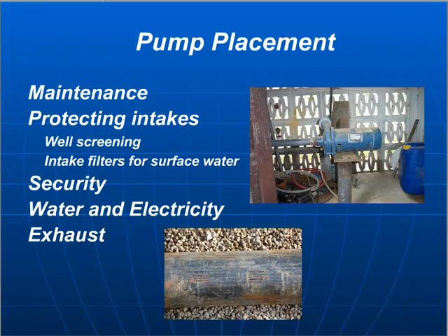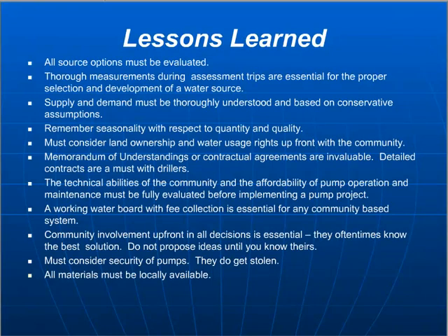It's also important to think about the housing of the pump itself, where it's going to be placed, and how it's going to be protected to ensure that it's not at risk for theft or vandalism, so that you're not having to worry about it. It's also important that it's not in an area that's going to get flooded and damaged that way. I've worked on a few projects where that's happened, where the pump was along the side of the river and a big flood came and the pump got carried down the river, and so they had to start over the project. So there's a variety of different things to consider just in the placement itself, and if there needs to be some sort of housing, and if so, the spacing, so that you can repair the pump as necessary.